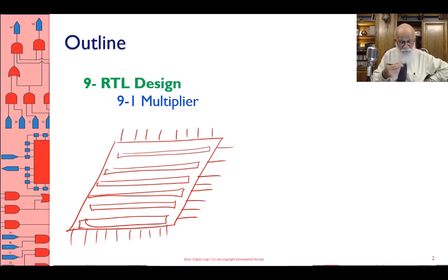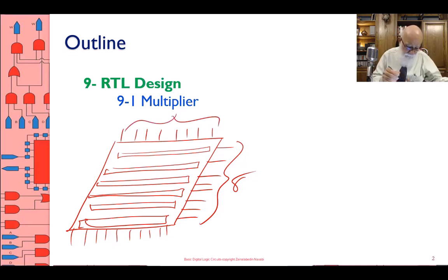So I have to have 8 rows of 8-bit adders put in diagonally. So that works, but then the problem is that I have 8 8-bit adders for operands of 8 bits. This is A, this is B, both of them 8 bits, and then I have this.